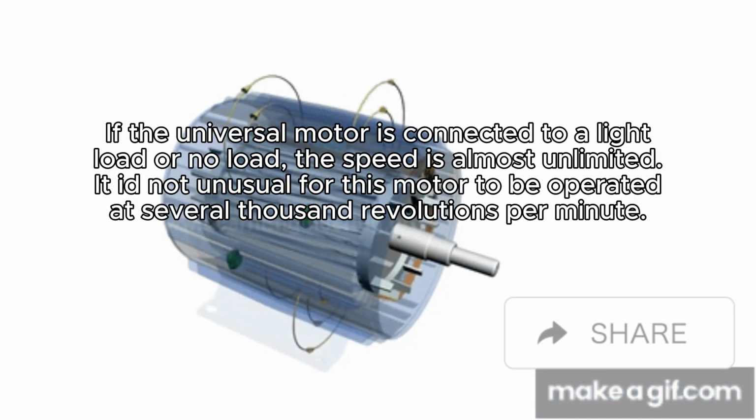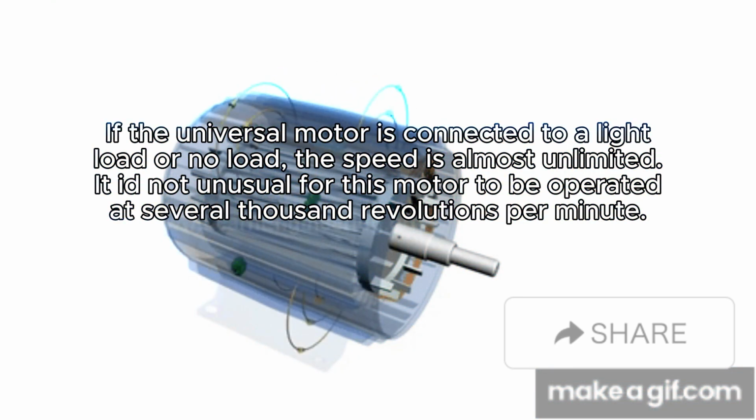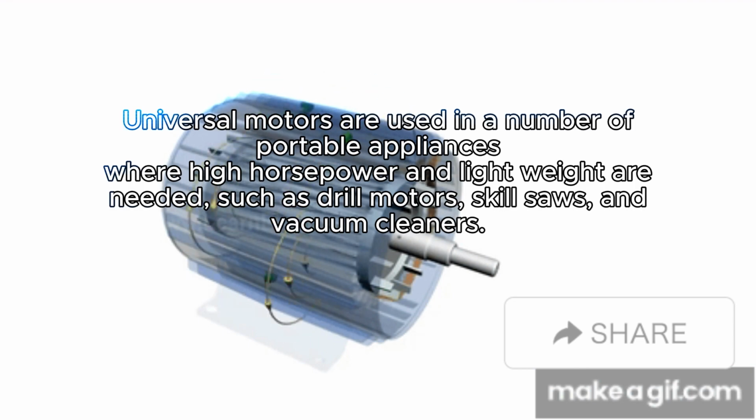If the universal motor is connected to a light load or no load, the speed is almost unlimited. It is not unusual for this motor to be operated at several thousand revolutions per minute. Universal motors are used in a number of portable appliances where high horsepower and light weight are needed, such as drill motors, skill saws, and vacuum cleaners.